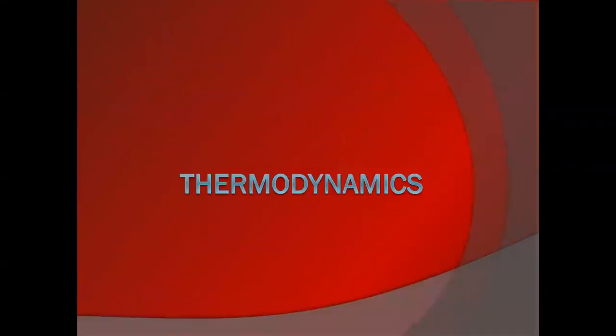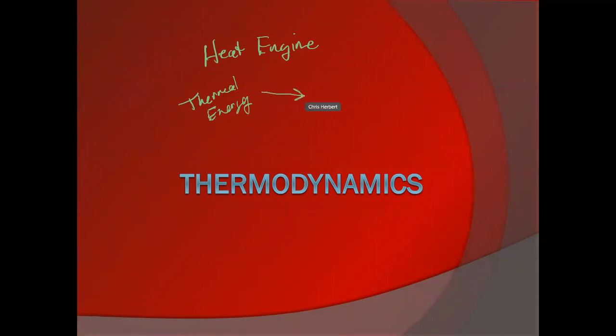Again, the whole idea is with the heat engine, it's some type of device that's going to turn the thermal energy. Okay, and this thermal energy can come from combustion. It can come from heating a boiler up with wood, with coal, natural gas, with oil, and allowing that thermal energy to cause either a gas or a liquid to expand. As it expands, it's going to push on a piston, and this is going to do work. We know work is mechanical energy.